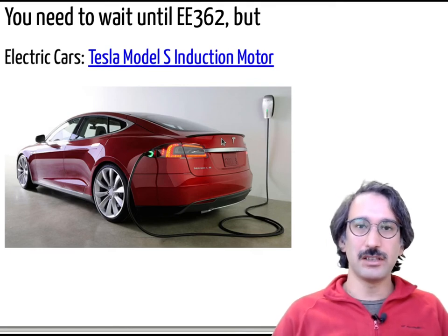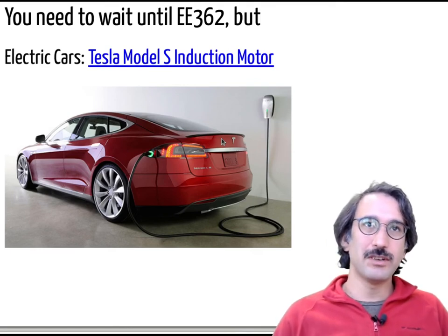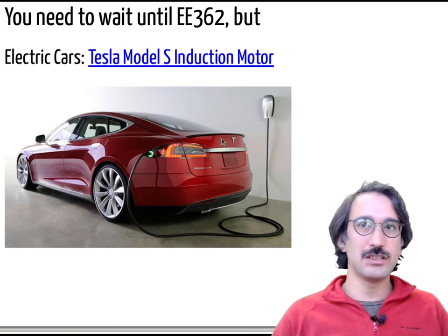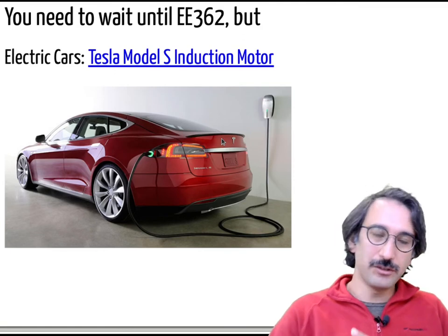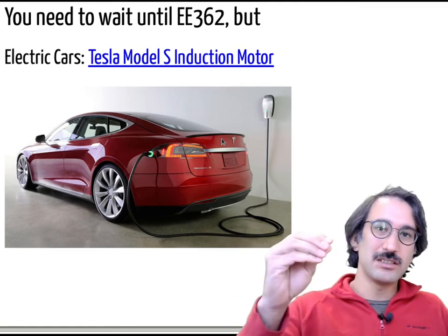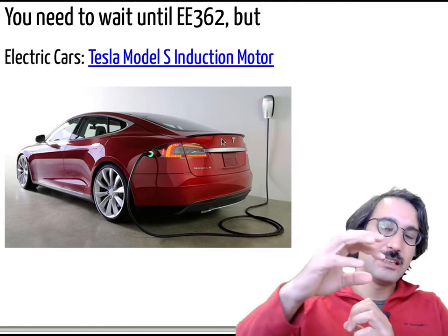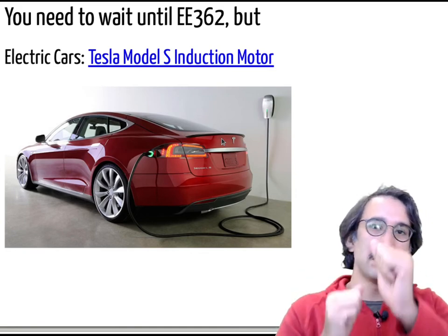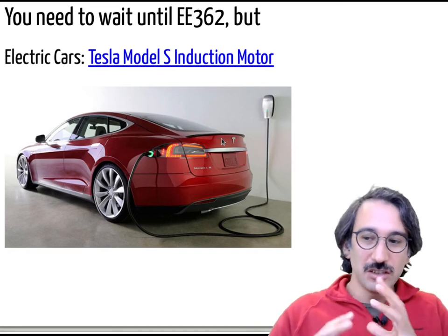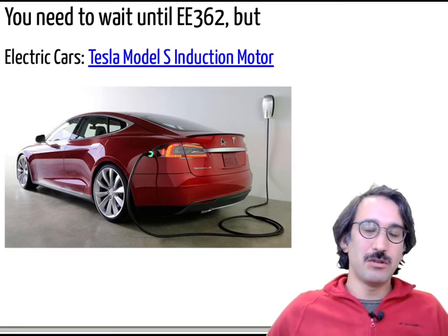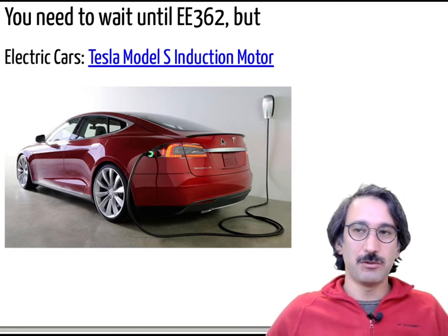especially during startup. So it gives them huge advantages over internal combustion engines, because in an internal combustion engine you put your foot on the gas pedal, the injector sends some fuel, they get some air, and then the piston starts moving up and generates some torque. You need to change gears to operate the internal combustion engine in the most optimal condition.